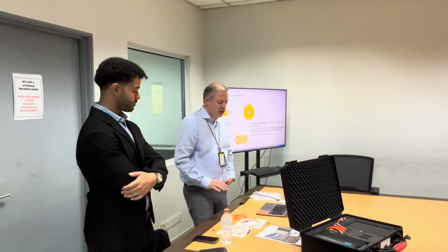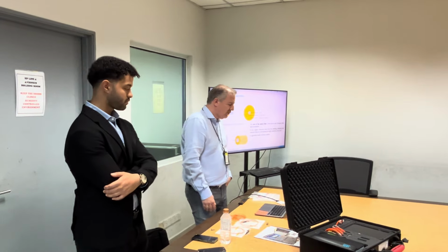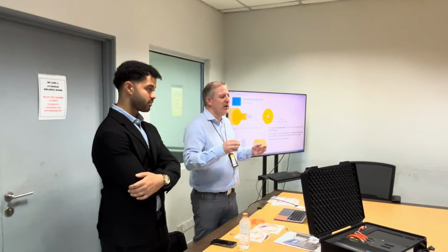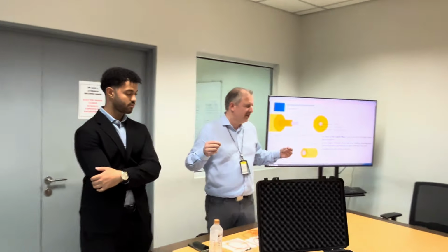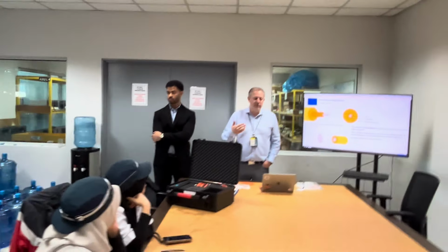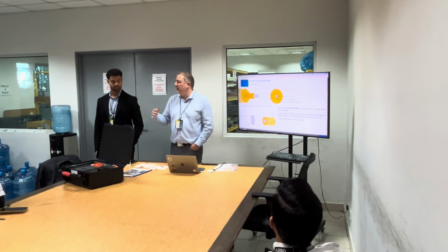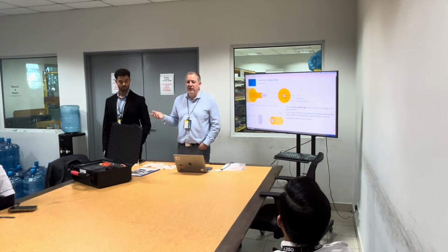Just a quick introduction of fiber optics. So fiber optics is usually used to transmit light. We use it in aviation mostly because it helps to transfer a high volume of data, and it's not sensitive to any EMC.